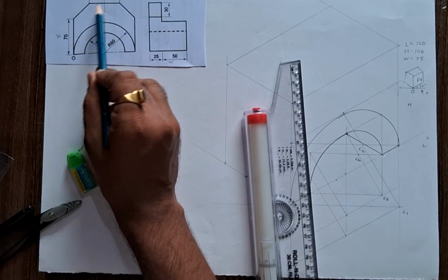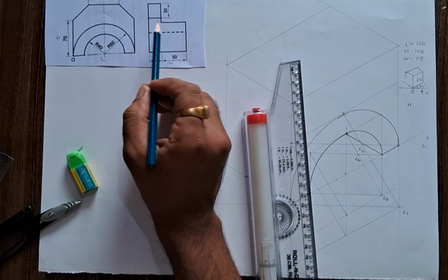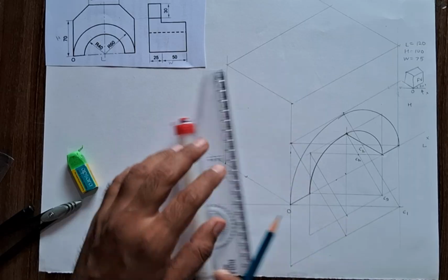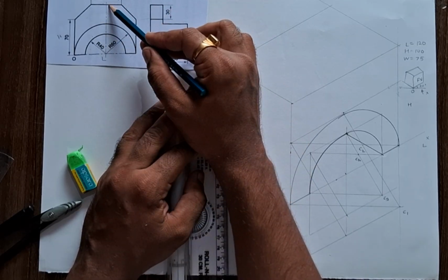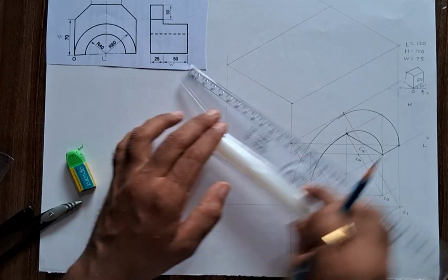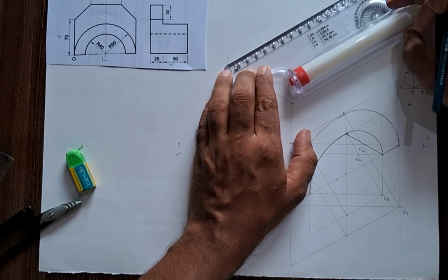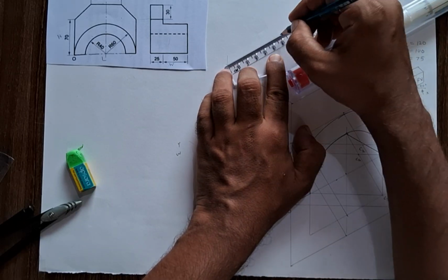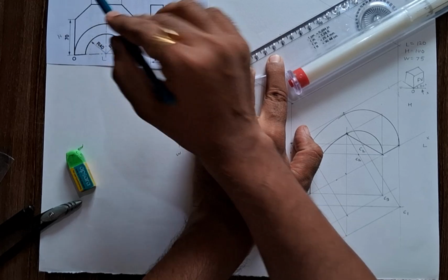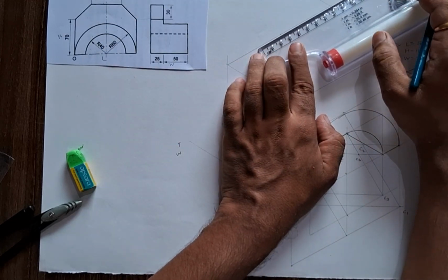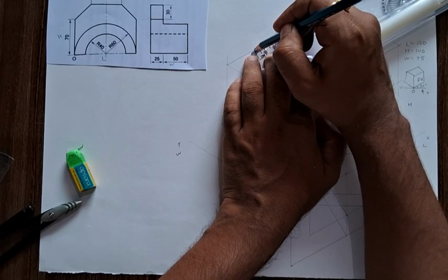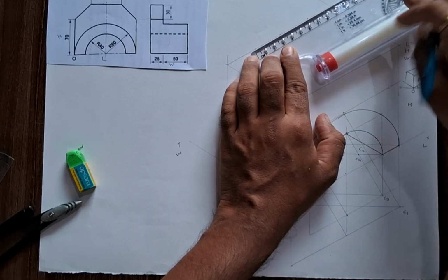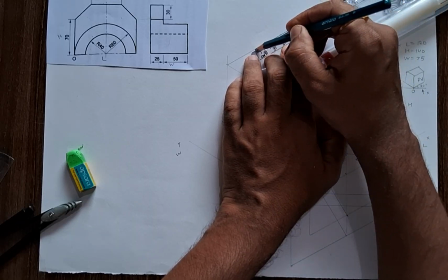this vertical wall, its thickness is 25 mm. So we can mark this vertical wall. This 60 mm distance is at the center. So we know that this is the length, and along the length we can mark a midpoint. The straight distance is 30 mm. So 60 mm, from the midpoint we can mark 30 and 30 mm. This edge we can see.